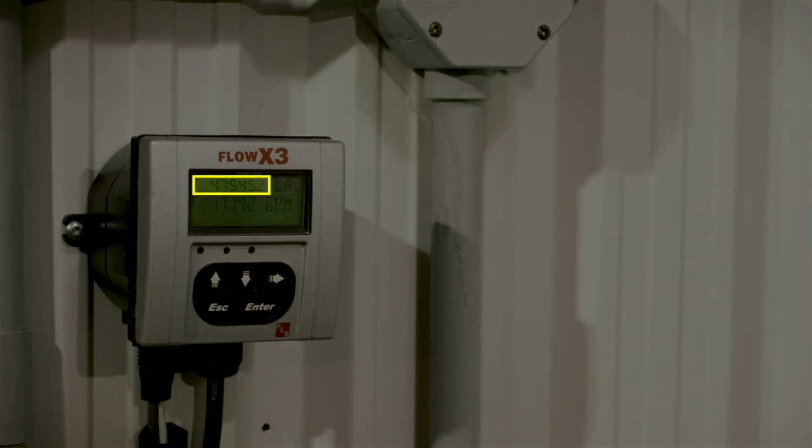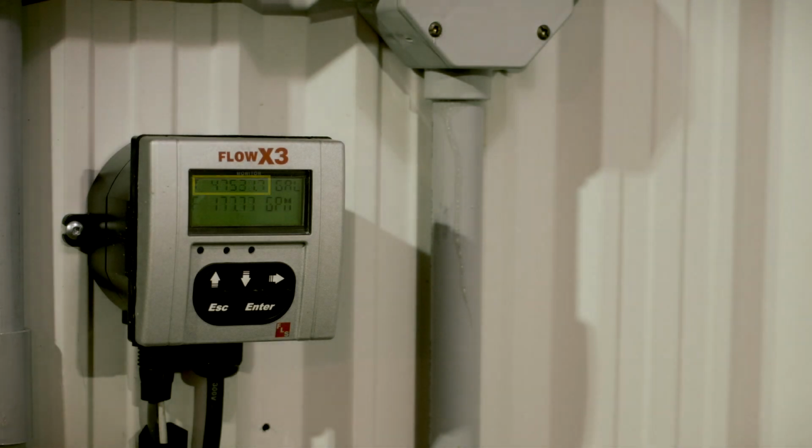Totalizer, or the total flow reading, is the total volume of water that has passed through the meter. Total flow readings are typically measured as a running total. Therefore, the total flow number may represent the volume of water that has passed through the meter since it was installed. The totalizer number can also be reset by following the manufacturer's instructions on how to do so.